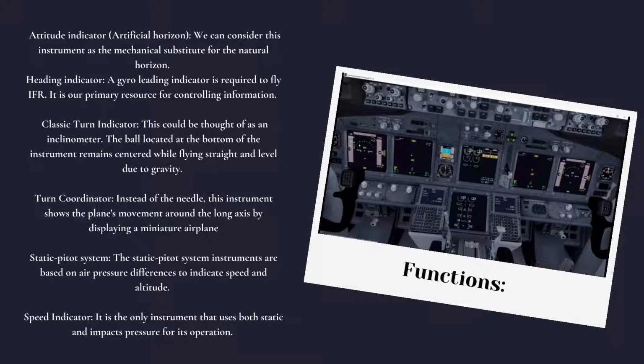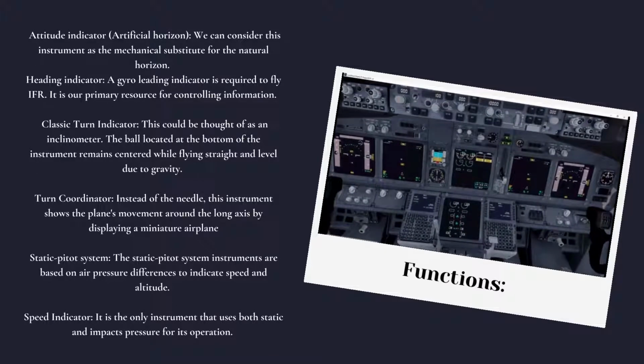Turn coordinator. Instead of the needle, this instrument tracks the plane's movement around the longitudinal axis, displaying a miniature airplane. The motion of the aircraft is proportional to the rate of turn. The conventional inclinometer ball is also part of this instrument.